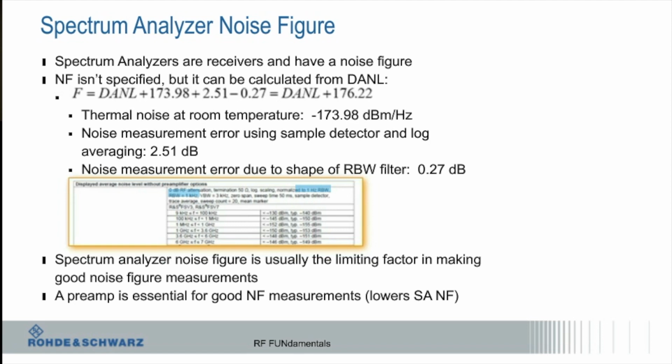What's the difference between a spectrum analyzer and a network analyzer? Good question. It's a bit of an aside, but that's no problem. A network analyzer is first off a stimulus response device. I'm putting in a signal, and I'm looking at what the resulting signal is. It only generates and analyzes sine waves. Anything else it does, time domain or whatever, is math it's doing, but it's purely a sine wave device, and it's really optimized for doing S parameters.